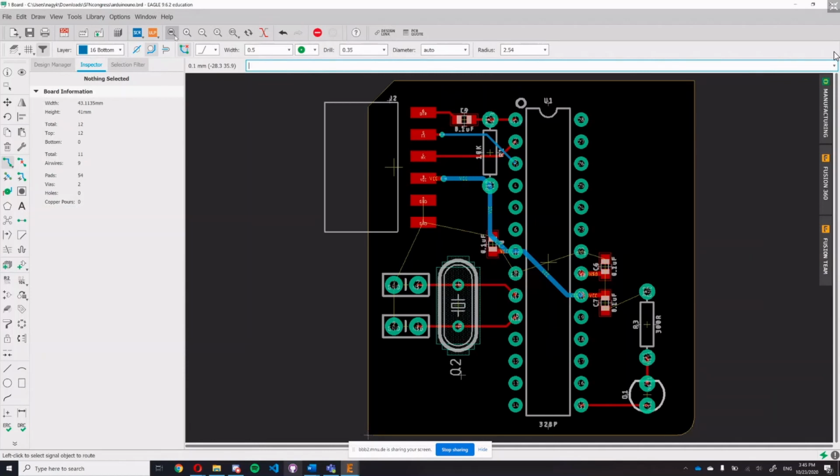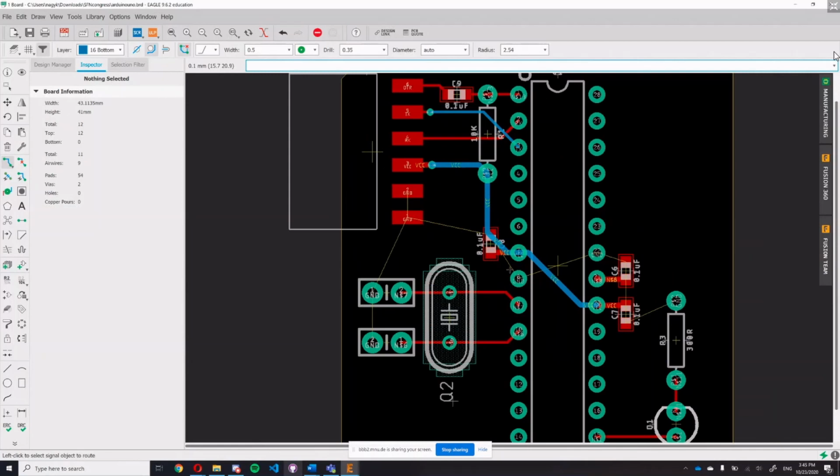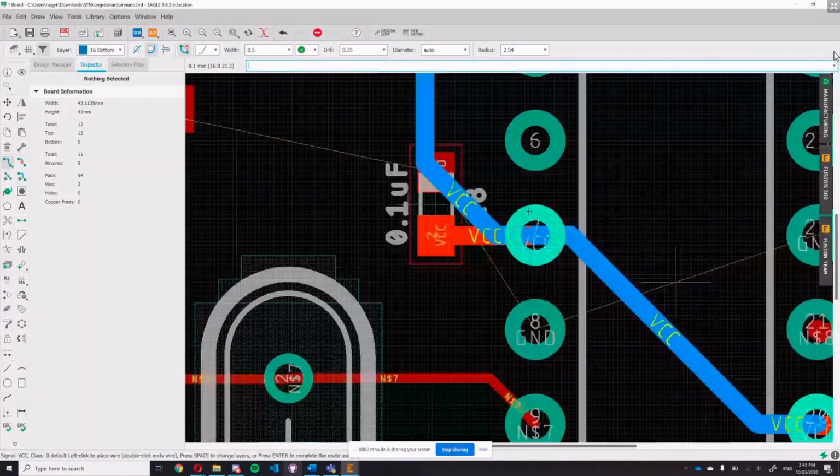You just have to watch out for the green VIAs because there you cannot route it just through. Then you do an electrical connection. I think that goes without saying, but I just wanted to add that. Yeah. You can route it through when it's the same signal, like here. That's totally fine. But if I would want to do this, then it won't even let me because it's smart.